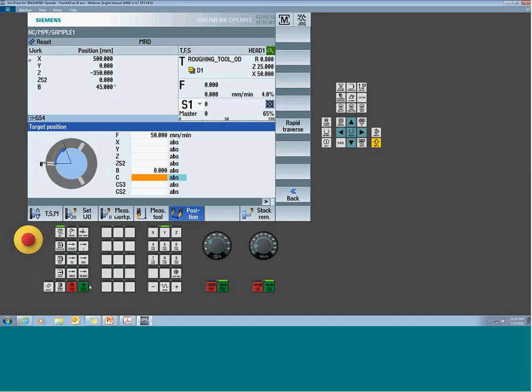So you want to be very careful when you start to move these machines around, and you're using the functionality where you're driving it through the beta and the gamma field, because that's going to allow the rapid calculation of the offset. So now I can go back. And I'm going to want to be in a safe spot, obviously, before I tell it to move, because it's going to swing that tool down. But that starts to track, allowing the system to manage the point in space where you're sitting.